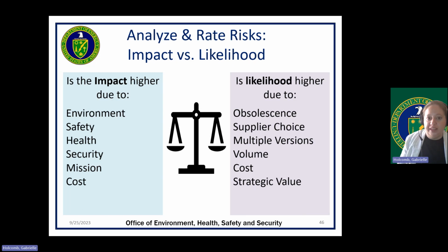Some items are more likely to be counterfeit, fraudulent, or suspect, since they have been historically and continue to be targeted by counterfeiters. These include obsolete components, difficult to procure items, items where lead times are critical, items where multiple versions are available, items where there is a high volume but low price, or vice versa, and common commercial items, items of strategic value, etc.